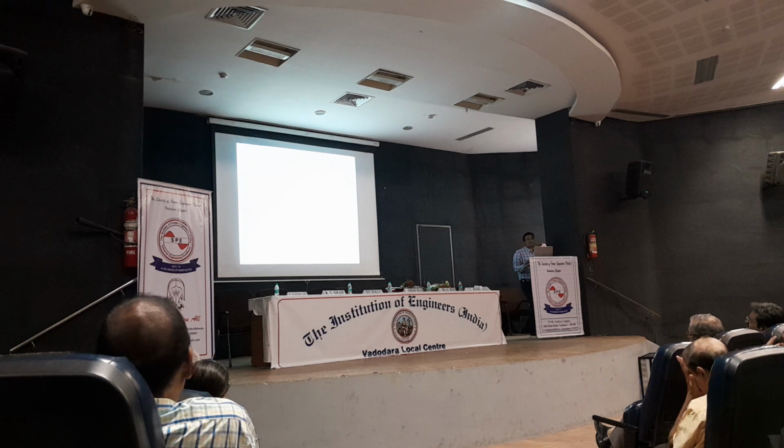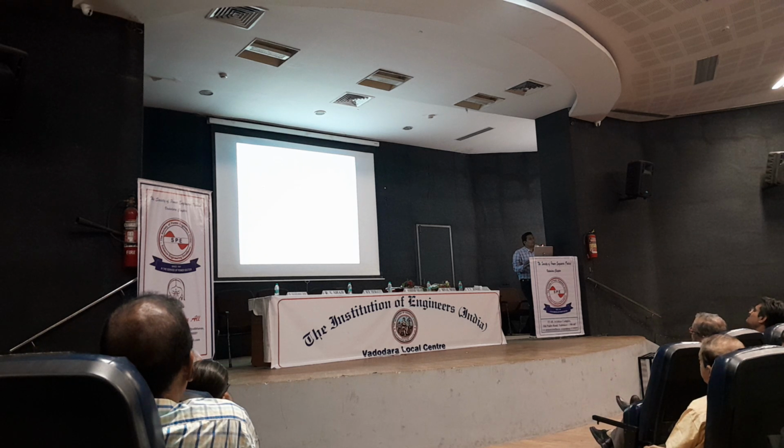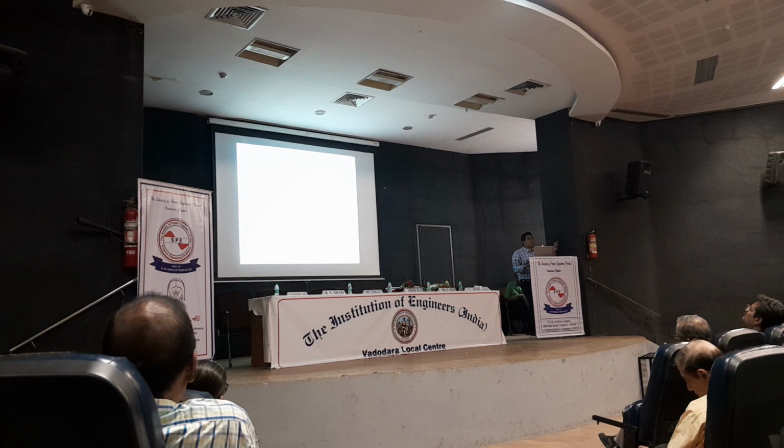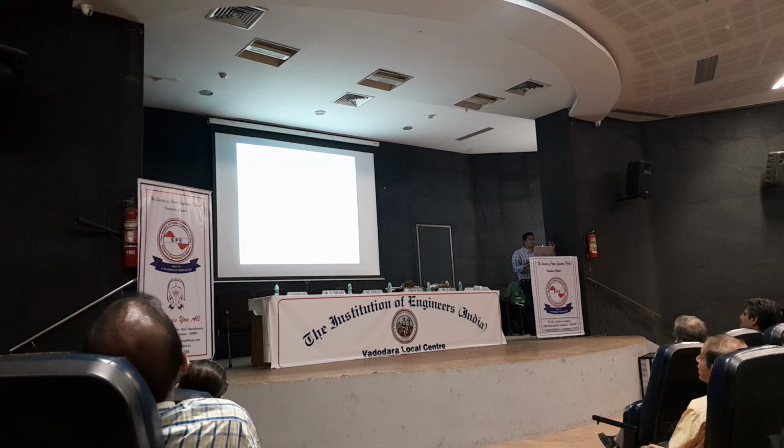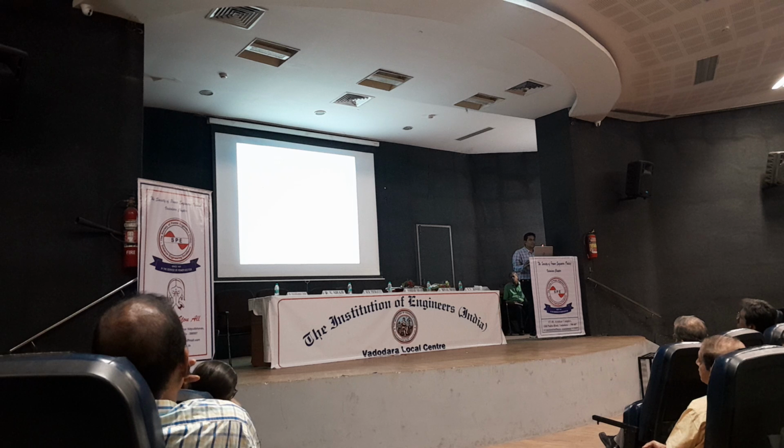We are trying to check what will be the effect of failure of either a generator, a transmission line, or a load. Because we are worried that if any of the components fails, what will be the impact of it on the rest of the system. That is called contingency analysis, and generally it is done in terms of individual elements, or in terms of a combination of lines, sources, or maybe a combination of anything: generation, line, load. So you can do contingency analysis.